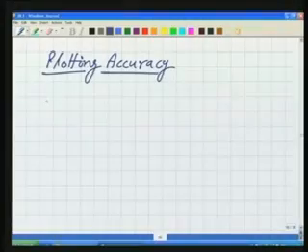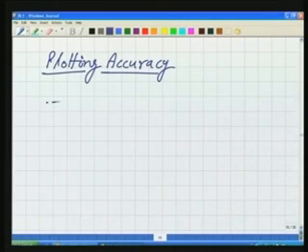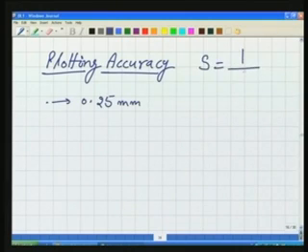Well, when we are talking about the plotting accuracy, there is a dot and the size of this dot is 0.25 mm on the map. What is it equivalent to on the ground? Well, if you are writing the scale as 1 by n, where n could be any number, for example let us say 1 by 100, what is the meaning of this?